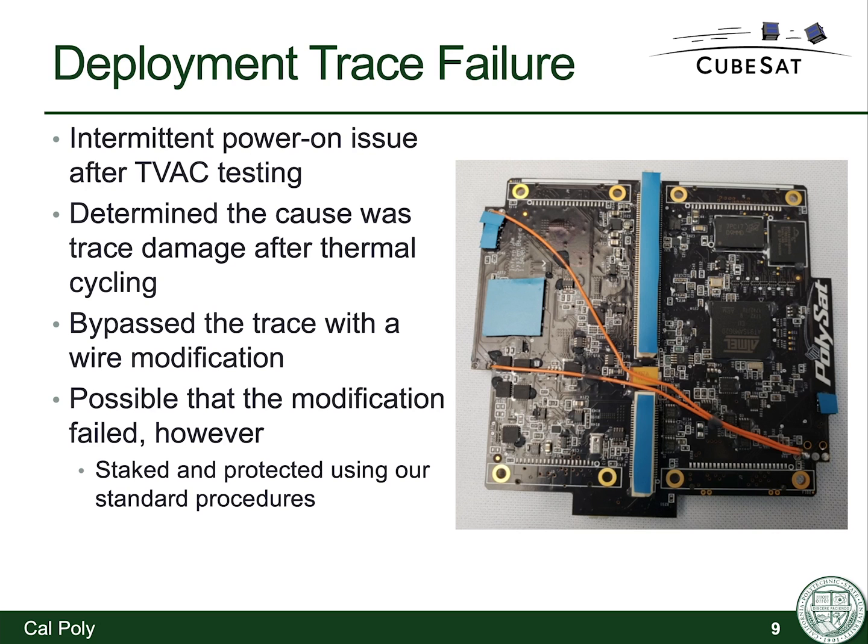The evidence we have that makes it less likely that this was a problem is that we were following our normal staking and wire modding procedures. So if you look at the picture, you can see where there's some staking on the wires. The wires are already low mass to begin with, but then we added staking to them to help remove the strain of the vibrations environment. So the chances that they physically separated from the solder joints or physically broke as a result of the launch environment are fairly low.